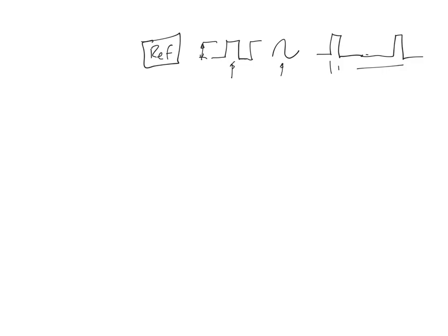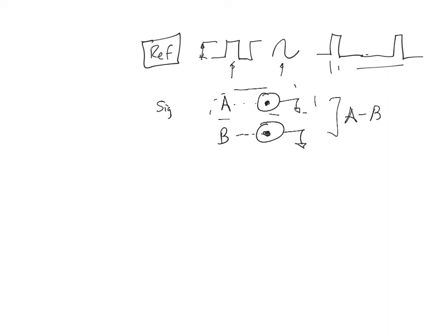Okay. Then you're going to take your signal and you're going to put it in. There usually are 2 inputs on a lock-in, A and B, and they are on coax inputs. B is the center conductor on the B coax input. A is the center conductor on the A coax input. The outer shells are grounded typically, and often you'll just be wanting to do one wire, so you'll click a switch that just says pay only attention to this. Sometimes you'll want to use 2 wires, and you can lock into the signal that's contained on A minus B. That's just a detail to know about to let you know that the signal has to be there, or the switch has to be set to the right thing.